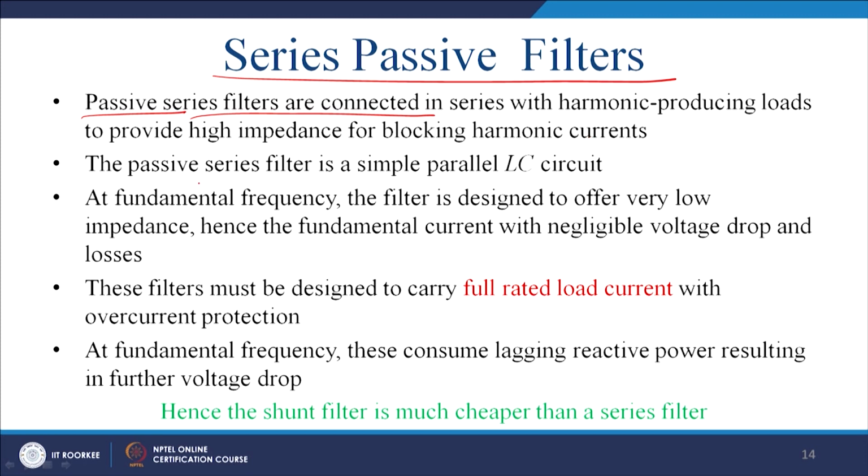The passive series filter is a simple LC parallel circuit. It is quite easy. At fundamental frequency, the filter is designed to offer very low impedance, hence fundamental current is negligible, and the voltage drop and losses are also negligible. But the problem lies in that, since it is in series, it sees the whole current through it.